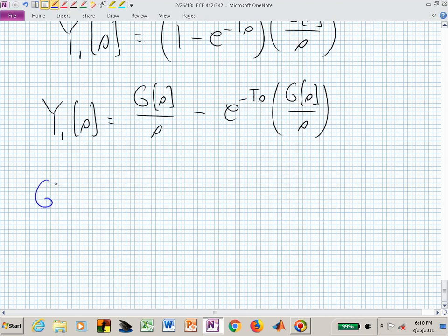Well, we want to now convert that into a capital G of z. Well, how do we do that? First, we're going to have to take that back into the time domain, so we need to inverse Laplace transform that. We'll sample that, and then what will we do with that sampled waveform? We'll z transform it. That's what I'm trying to now show in this next line, so don't get too hung up on all the detailed notation. What did I say? I want to inverse Laplace transform that, then sample it, and then z transform that sampled signal.